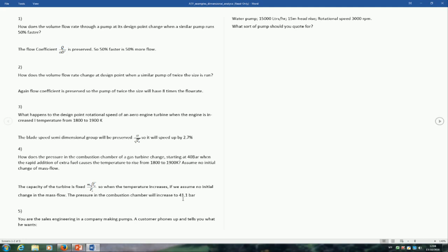So you can't really test out the behavior of a compressor inside a gas turbine because the turbines don't let it move. What this allows is that we can move it, because by putting in the extra fuel, making the temperature and pressure go up, the compressor suddenly has to generate more pressure rise, because that's ultimately where the pressure comes from, is from the compression system.